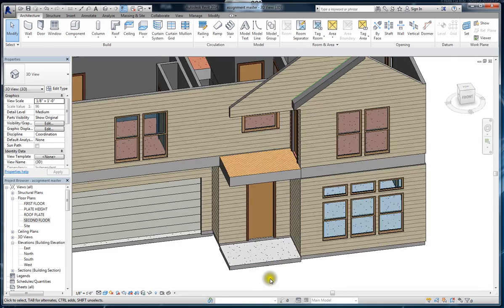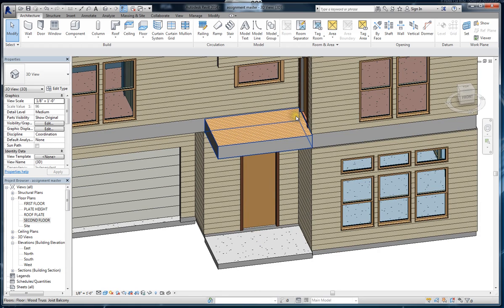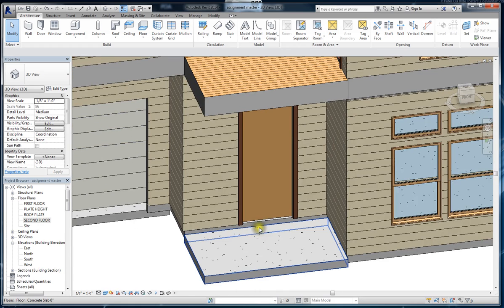And so why do we do 3.5 inches down here and only 2 inches up here? Well, the 3.5 inch is the exact same dimension as a 2x4 stud. Whenever the contractor is forming a concrete slab, they use dimensional lumber to form the edges and to form any level changes on the slab. So a 3.5 inch is a 2x4 on its side. So when they're forming the slab and using this lumber, they just put a 2x4 vertically, and that's where you get the 3.5 inch. And then they pour the concrete and smooth it out to that level.